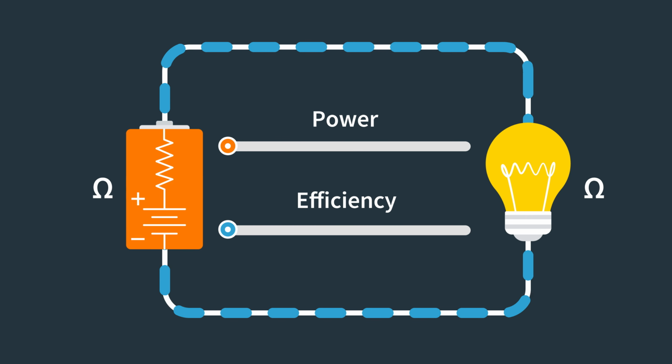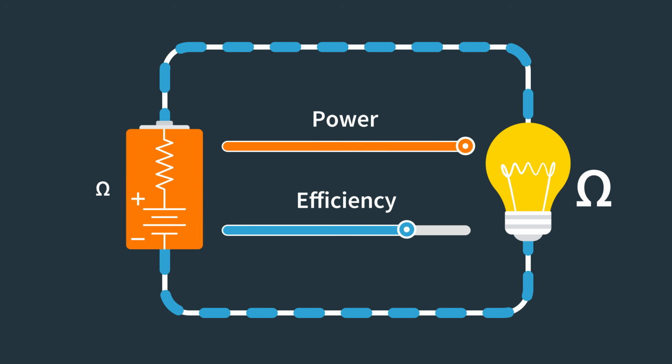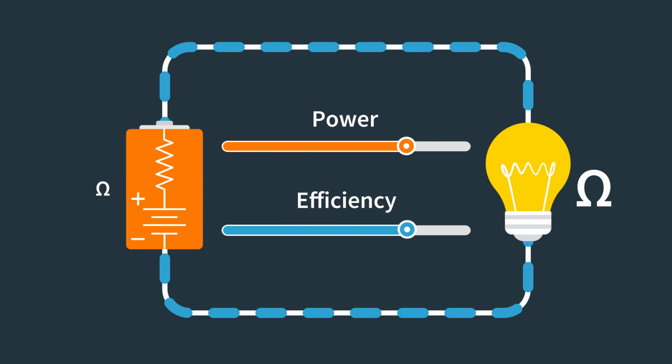It's important to understand that the maximum power transfer theorem isn't a strict rule, it's just a design guideline. It shows us where the trade-off lies between power and efficiency. When the load equals the source resistance, power is maximized, but efficiency is 50%. As the load increases, efficiency improves, but delivered power decreases. The right balance simply depends on your goal. Yet, understanding this principle helps engineers design everything from audio amplifiers and communication systems to power grid and renewable energy setups.